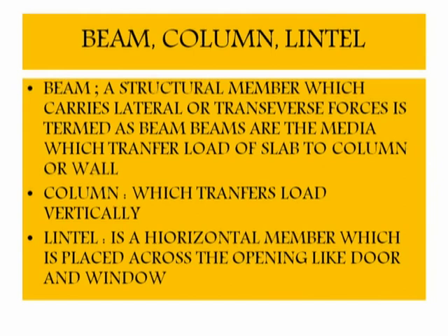Then the column transfers the load vertically. As we have seen earlier, the beams take the load from the slab, and the beam transfers the load to the column. Columns take the load from the beam and transfer it to the foundation. Lintel is a horizontal member which is placed across an opening like a door and a window.